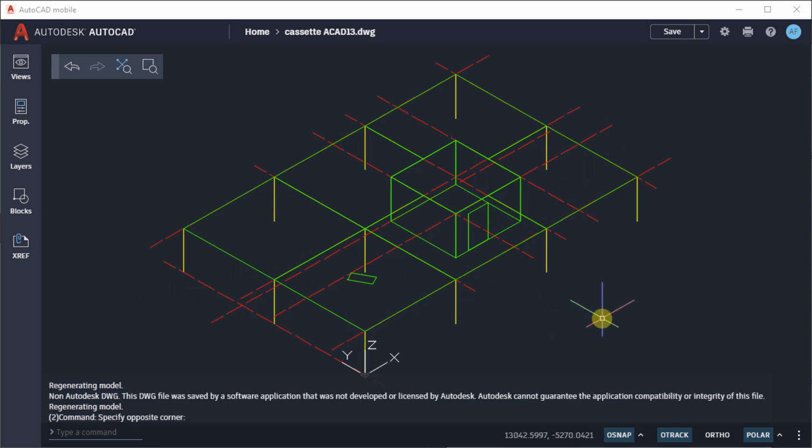In terms of AutoCAD, the columns, the yellow lines, are simply just lines in AutoCAD nomenclature. The red lines, the grid lines, I've defined as lightweight polylines, so the standard polyline type in AutoCAD. The green are essentially closed 2D polylines or heavyweight polylines in AutoCAD. So that forms each of the floor panels, it forms the opening, it also forms the core itself.